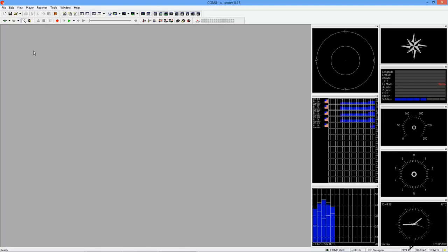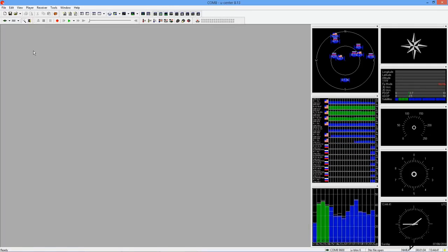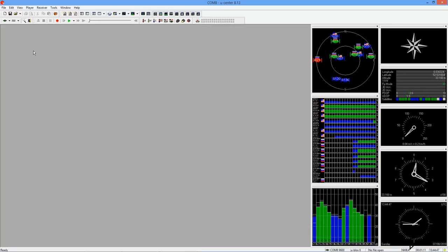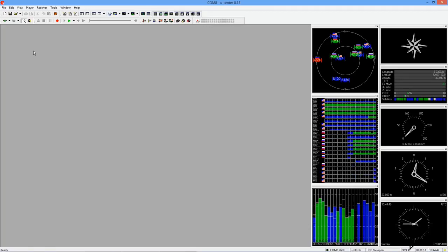When I power the GPS module, it will start to detect satellite signals. This may take quite some time, especially when you are indoors. The backup battery is completely drained when you receive a new GPS module and it needs to create a new dataset for tracking the various satellites. If the GPS module cannot find any satellites, you might need to take it outside. The progress of the GPS module can be followed in the main screen of the uCenter software.